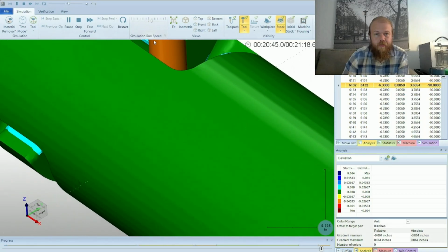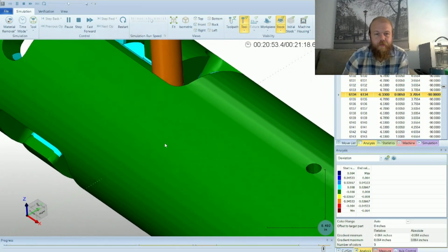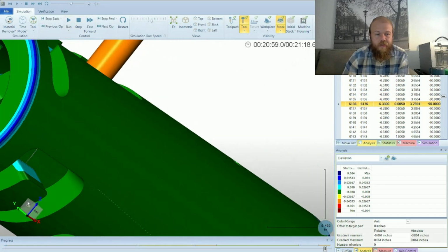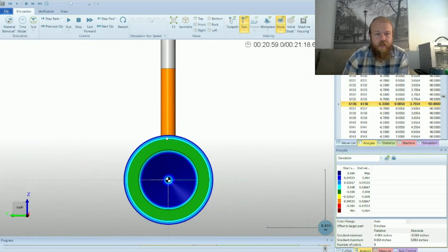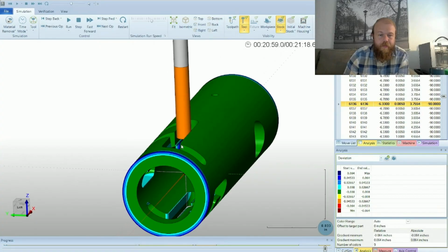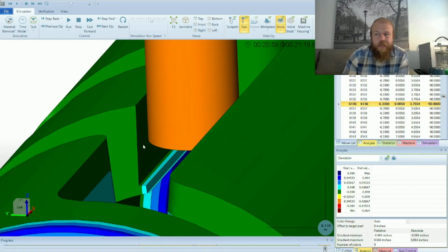And it'll get down to the bottom there. And then you can see as it's machining, it's off of the center line of rotation, just a fraction of an inch there, but it's going to be able to move in X, Y, and Z, and the A axis, all 4 axes simultaneously in our 4-axis Pro. And we'll cut everything to size there.